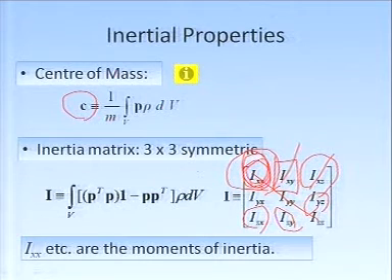But if there is a matrix where only the diagonal terms are non-zero and all the others are 0, then these moments of inertia become principal moments of inertia. Okay? And we have used similar techniques to find out the stresses. Similar concepts were used with Mohr circle in our strength of materials classes in our undergraduate studies. Here it is a similar concept.